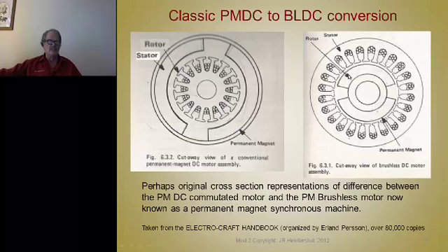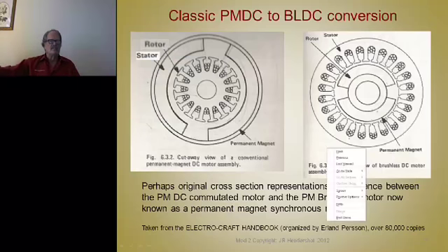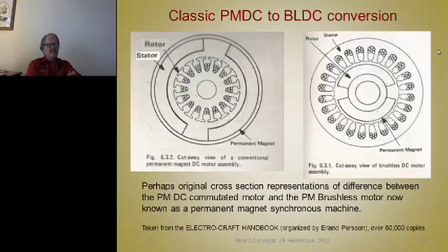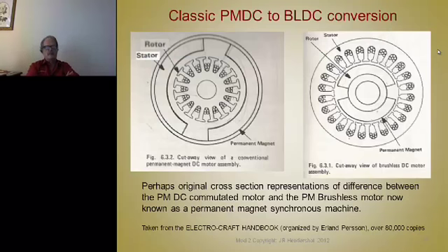And you don't even make a brushless motor that looks like that, but it's conceptually an inside-out brushless motor. So the word BL stands for brushless DC motor. That's where BLDC comes from. It had nothing to do with what the shape of the back EMF is. A lot of people think it did, but it had nothing to do with that at all.